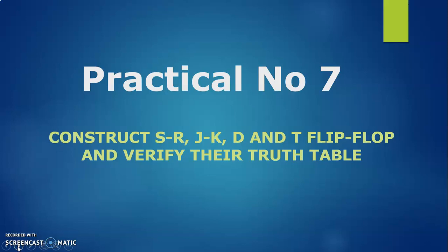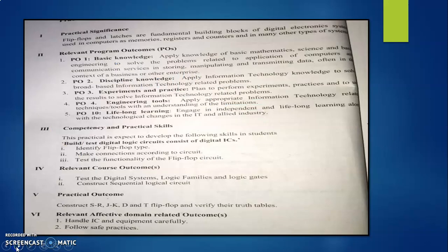So this is the flip-flop, a 1-bit memory cell, and flip-flops are sequential circuits. The sequential circuit depends on the present input and the past output. Memory is necessary in the sequential circuit because we store the past output and input. The clock input is also necessary. With flip-flops we build registers and counters. So this is the small introduction about the flip-flop.